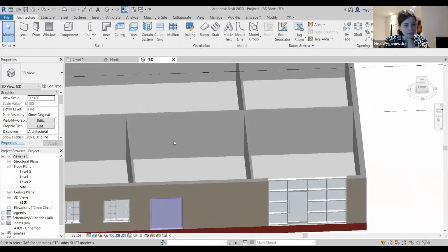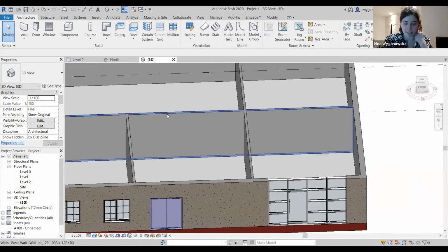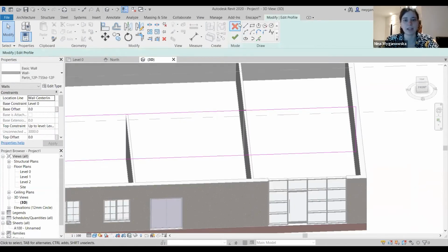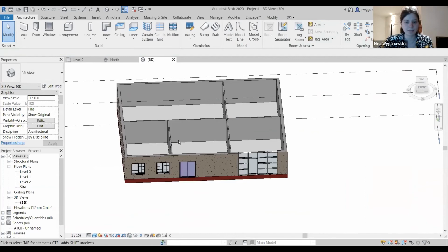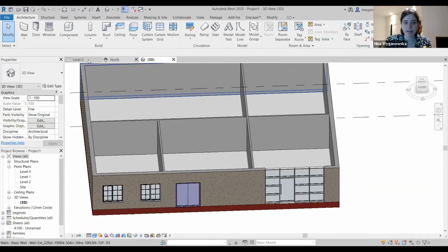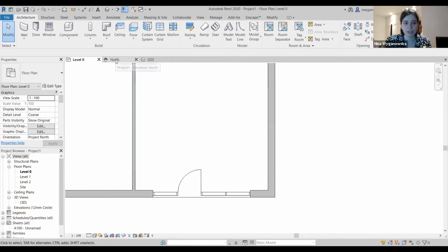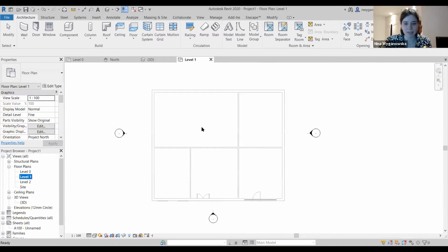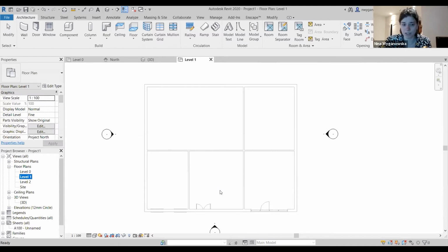And you can put the windows, doors, anything basically inside. If you want to change the wall type, you can go and click other wall type and all the other elements within the building itself. And then I was thinking that we can maybe put a roof on it. So if you go to level 1, you kind of see the outline, because all of your walls are kind of hitting the level.